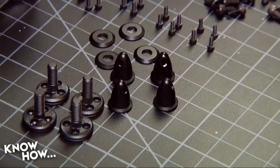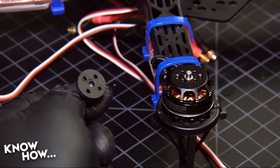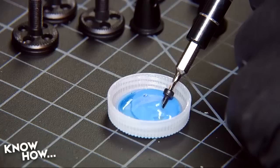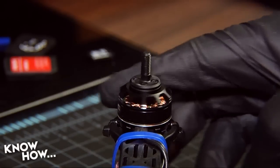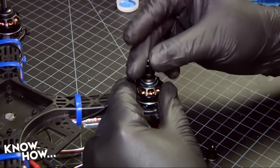Now let's attach the prop adapters to the motors. Each motor comes with a threaded adapter, a washer, spinner, and the screws needed to mount the adapter. Slip the adapter over the motor shaft, then fasten it to the motor casing with 4 screws, each lightly coated with Loctite blue. Once the adapters are properly fastened, drop a washer onto each motor shaft and fasten a spinner to complete the motor assembly.